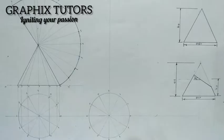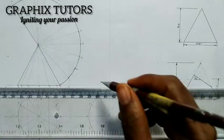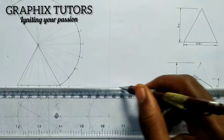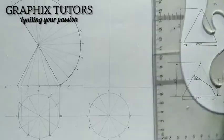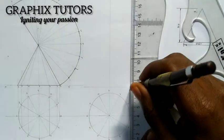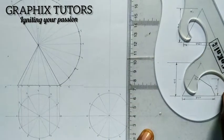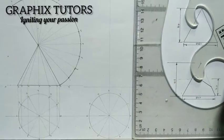Now the next thing is I'll just create a baseline. And this is another baseline to be very close to this. It can be at any length, right? So I'm going to project all those points up. I'll project this point up here to here with the help of my T-square. Don't forget. So here to here.